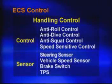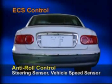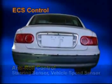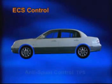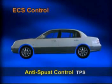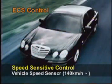As for the control related to the handling, there's an anti-roll control, anti-dive control, anti-squat control, and speed-sensitive control. The anti-roll control uses the steering angular velocity and the vehicle's speed. Anti-dive control uses brake on-off information and the vehicle speed signal, and the anti-squat control uses the TPS signal. Besides, the speed-sensitive control begins to apply when the vehicle speed is over 140 kilometers per hour, providing the hard damping force.